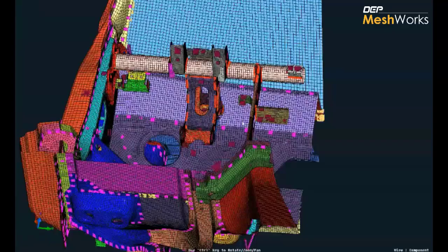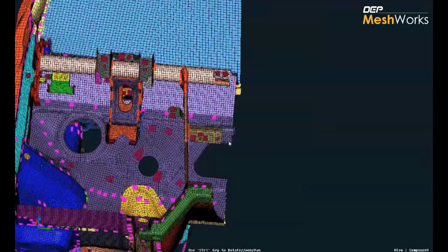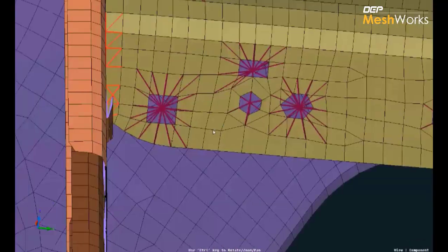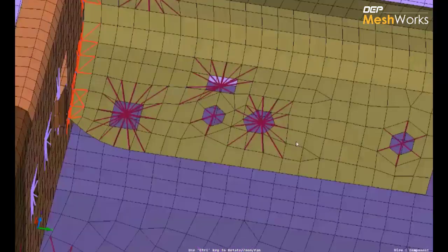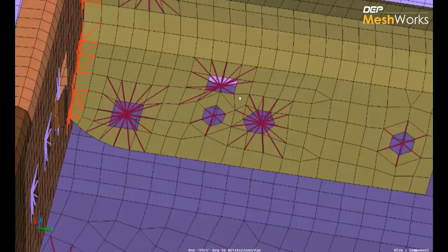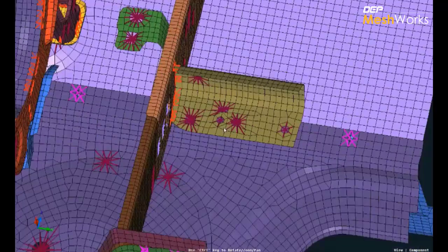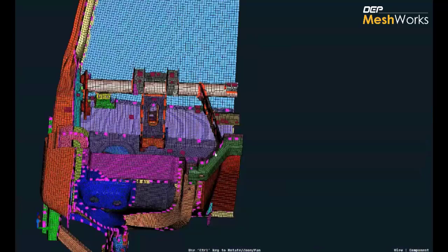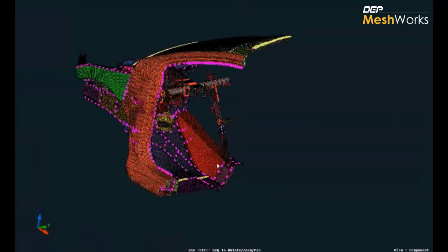beam. And also rigids which do not have the connectivity. So here we are just going to create a rigid patch. And here, as you can see, the regions are created with one layer. And in the case of dependency issues, the tool automatically identifies that if it is going to connect, it's going to cause a dependency issue. And in the local portion, it does not create that particular layer. So this is another scenario. The same integrated modeler can be used for vehicle side as well.